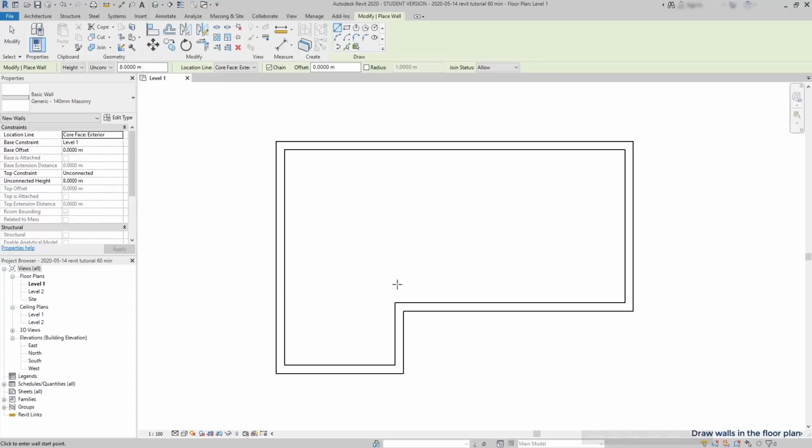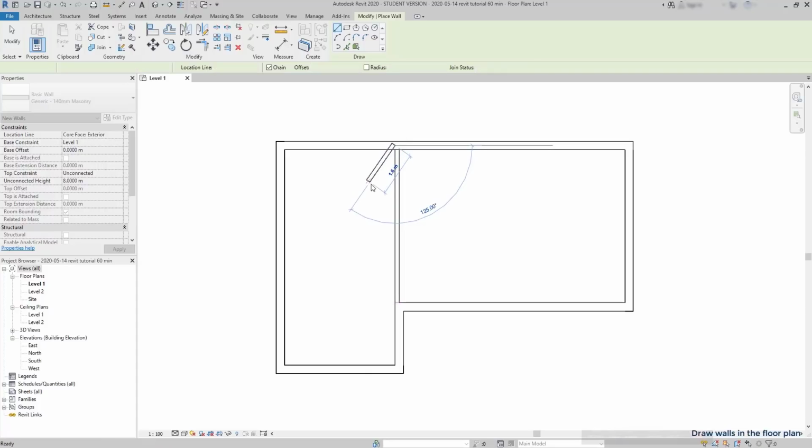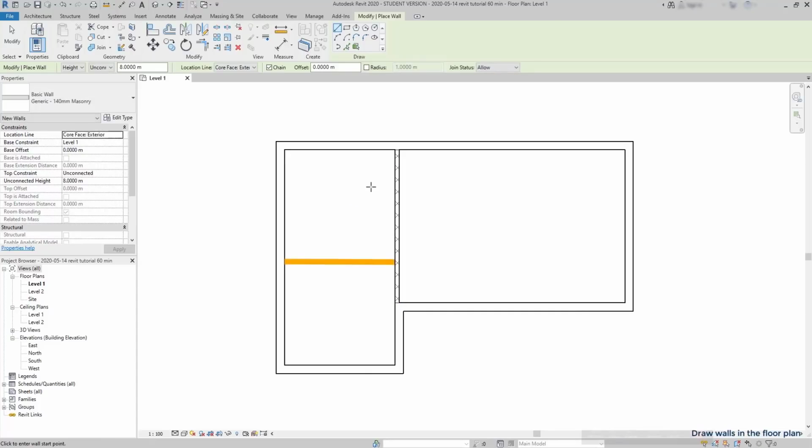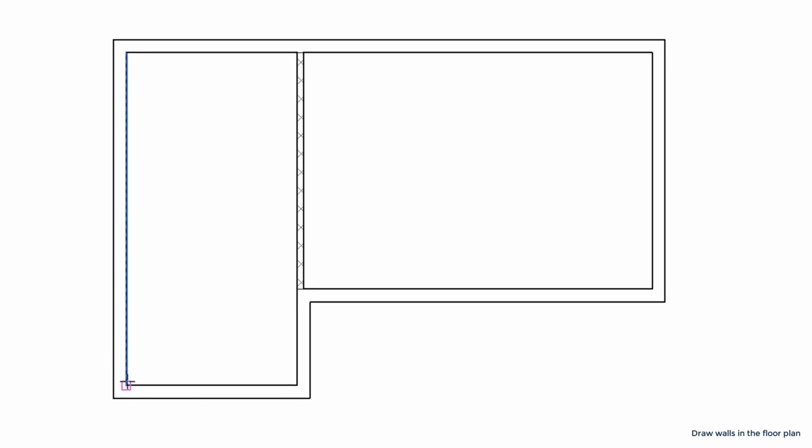And it's not very important which wall I start, because in Revit it's quite easy and intuitive to change the position of the walls after drawing. You will see. I start with this vertical one, because I know it intersects this corner. Then, the wall that divides the left part in 2 rooms is located at this distance of 3.8 from that external wall. One good way to make it is going to the endpoint at the corner, drag up and type the distance.